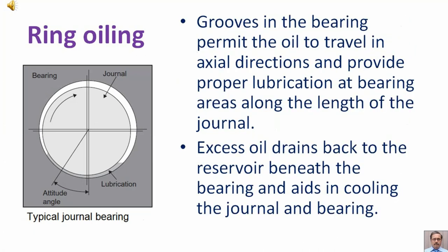Grooves in the bearing permit the oil to travel in axial directions and provide proper lubrication at bearing areas along the length of the journal. Excess oil drains back to the reservoir beneath the bearing and aids in cooling the journal and bearing.